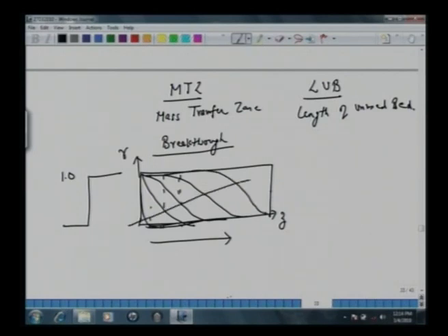So this would be increasing time, so that this bed is actually clean or very clean here. Then some more region gets challenged or gets saturated, so the concentration level rises. Then we have this another movement here, so slowly, this bed is now saturated till here. If we talk about this profile, now the entire bed is saturated here. So essentially we have these concentration profiles.